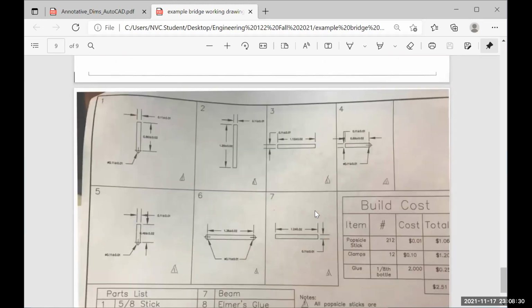So this is what we're looking for in terms of a set of working drawings. Working drawings is your overall assembly, any sub-assemblies that are necessary, your detailed drawings, and your parts list. So the way it's put together is in the order I just told you, with the assembly on top, sub-assemblies that follow, parts after that, detailed drawings after that of the parts, and then the parts list generally. The way it's read is backwards. So let's say I want to build what one of you is building.